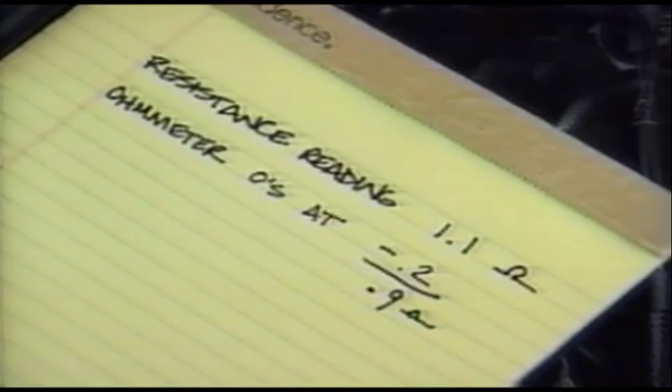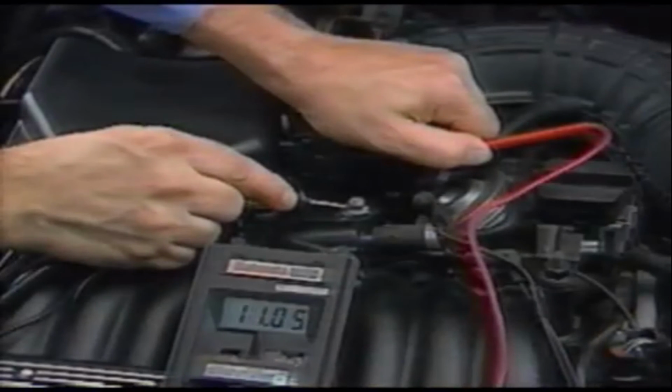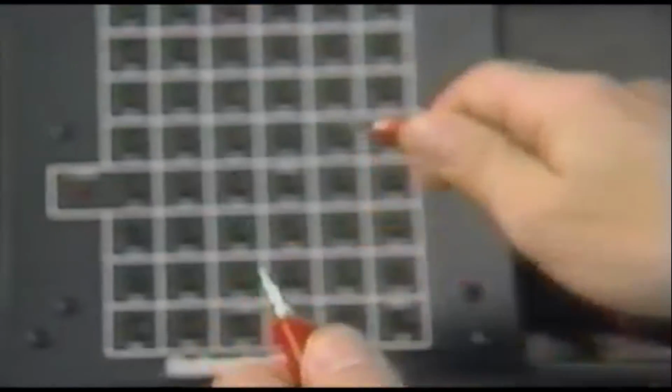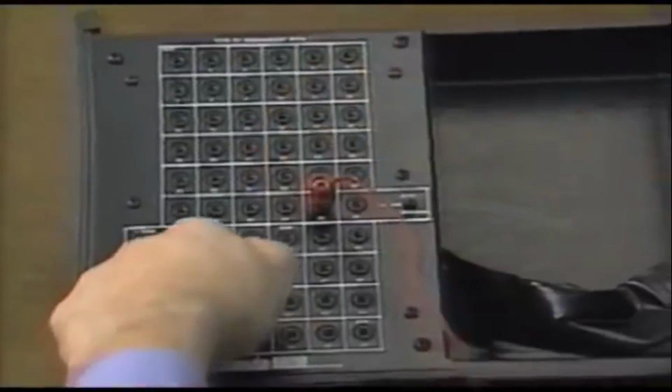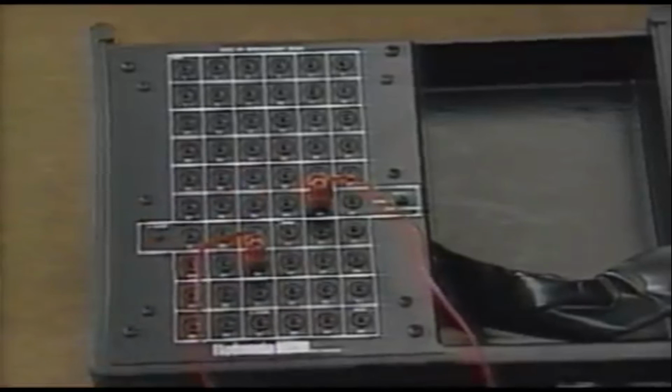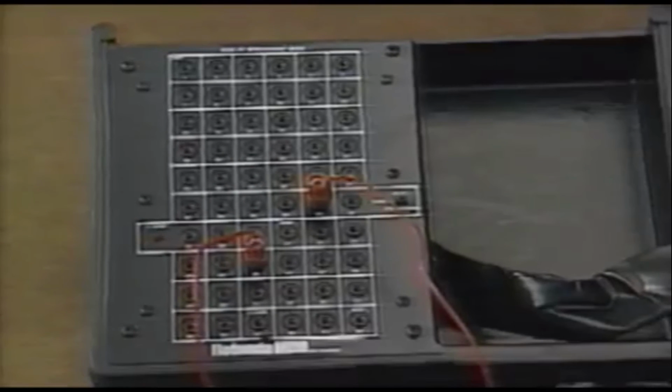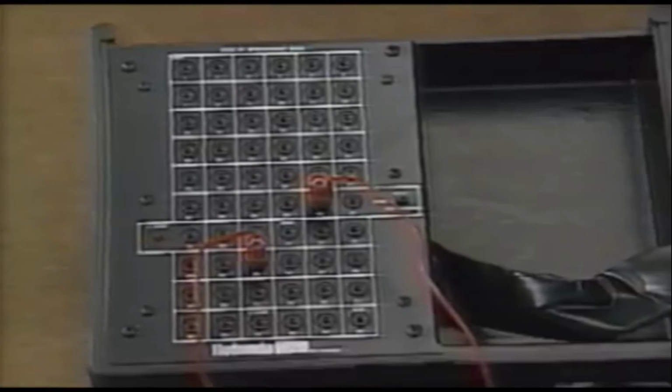When using a digital ohm meter, zeroing is sometimes automatic. When it isn't, simply subtract the resistance you get when touching the leads together from the readings you get during your tests. The DVOM is used to check components and circuits, including internal tests of input and output devices using a breakout box and jumper wires with compatible ends.